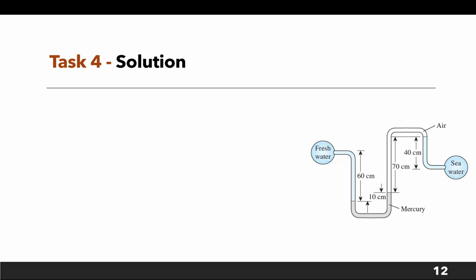So if we decide to walk through or swim through from this point, remember the pressure on the horizontal line is constant. We start from this level and identify the similar sections where we can easily cancel. I have mercury here, so going down here will cancel going up here. And then if I go to the air column, going up here will cancel this. So we are only going to consider this small height here, and then the 70, and finally this.